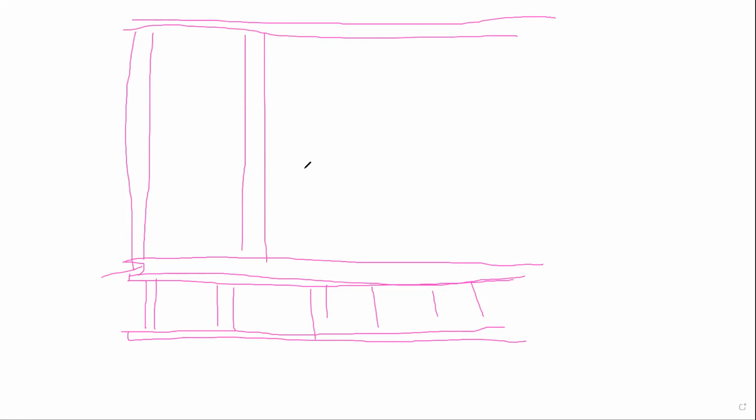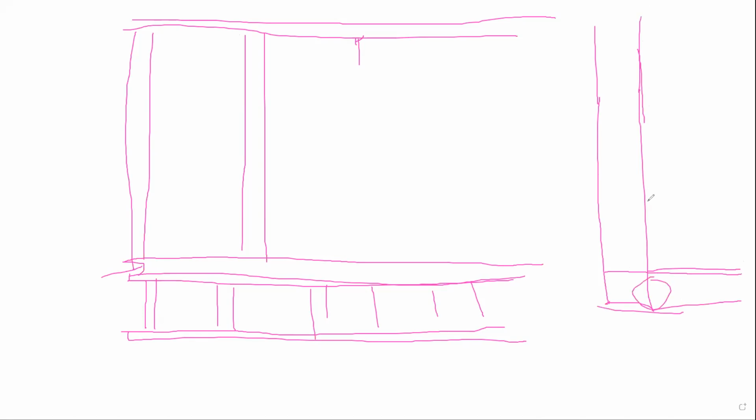Then once all the walls are built, for example, here, this is one wall like this, and at the corners here, that's one wall, and they just have one plate. Then they go ahead and double the plate. They take this top plate and bring it over here so that it locks the corner properly, and then they make this one butt up against it. That's how the second plate is added on, so that when the carpenter nails this, he's bridged that joint between the two walls.